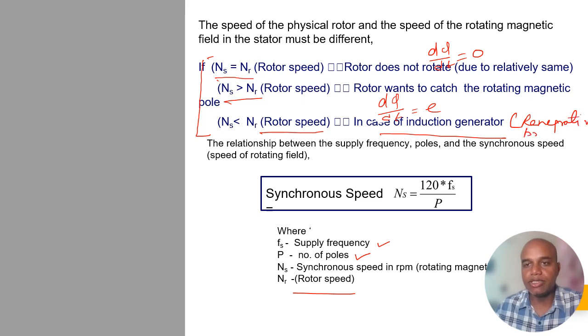Let's say my vehicle is going downhill. Very obviously my rotor is rotating due to the shaft movement, and if somehow I can manage for the synchronous speed to get lower than my rotor speed, because the rotor speed depends totally on the downhill slope, then as you go downhill, my rotor keeps rotating without any external supply.